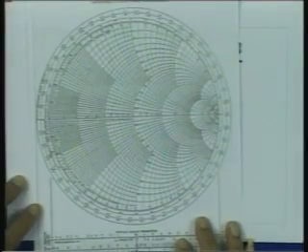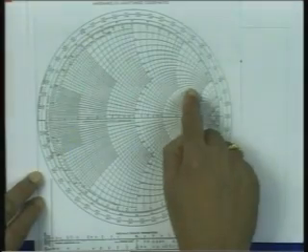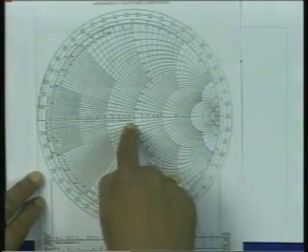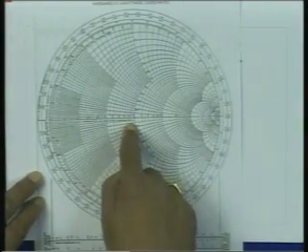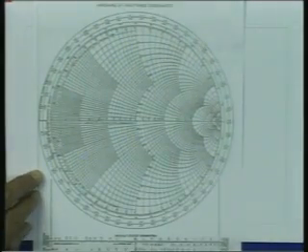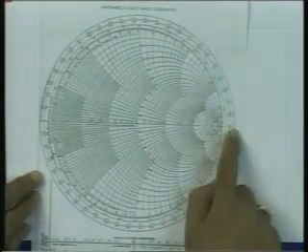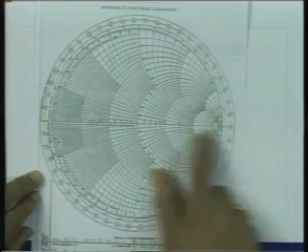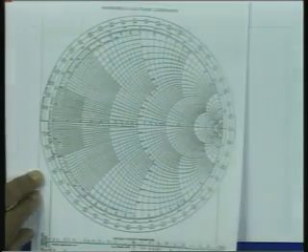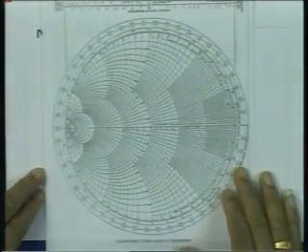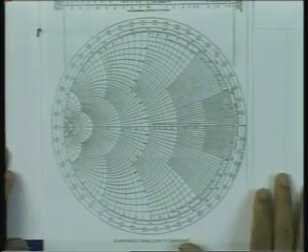What that means is, if I had initially a chart which looked like that, there is a rotation of every point of this around the center of the Smith chart, which is the origin of the complex gamma plane, by 180 degrees. So, if I keep the gamma plane fixed, that is, this is the real axis of the gamma plane, this is the imaginary axis of the gamma plane, then every point on this will rotate and the constant conductance and constant susceptance circles would look like that.